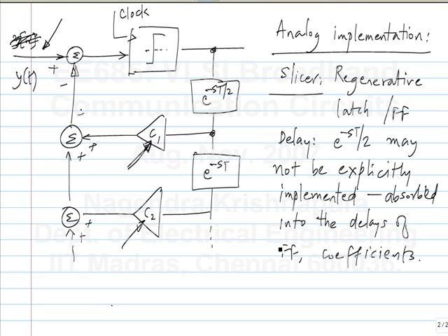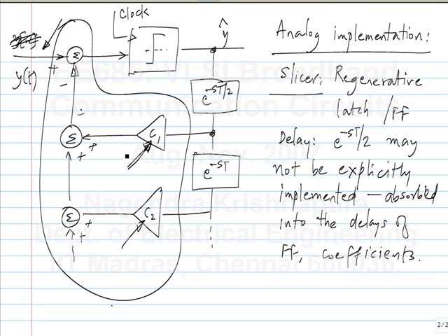How do we implement the coefficients? So in this case again these will be digital values, so you can use differential pairs in the switched region to implement it. Okay. In fact, this entire circuit does look like the transmit equalizer, where you have differential pairs with different tail currents which are tied together. Okay.